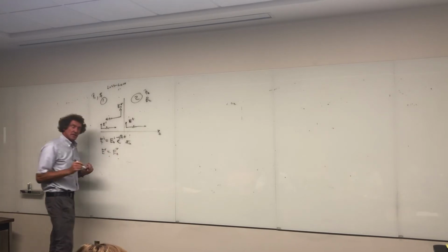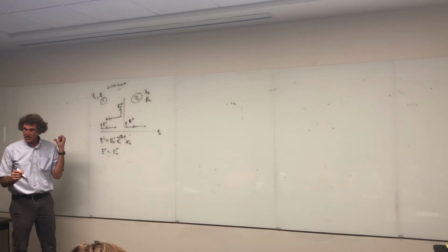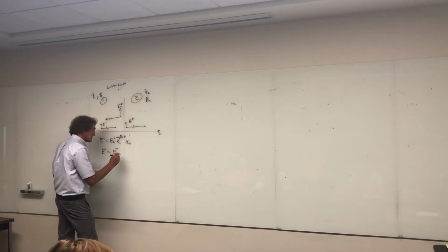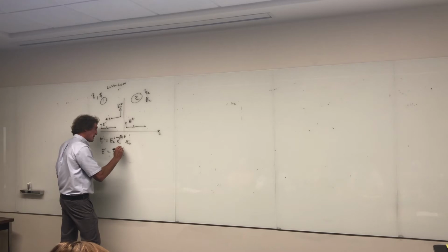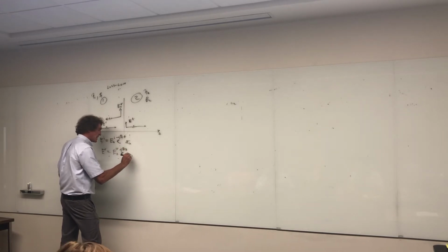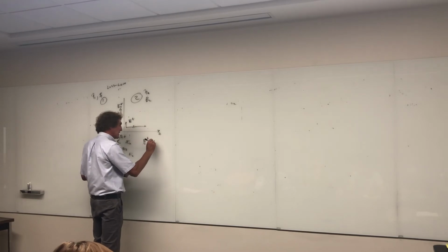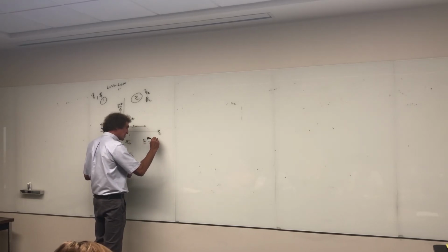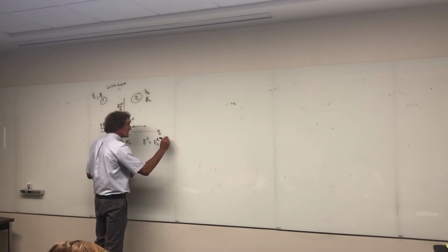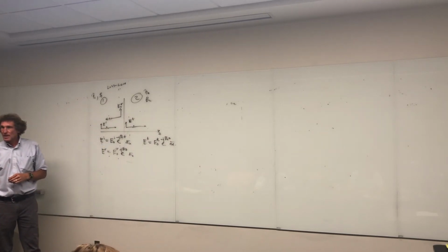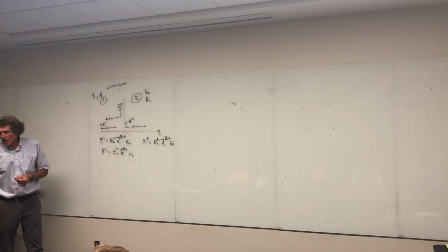Then what we're going to do is take E reflected, and it's going to have some E naught reflected, but it's moving in the opposite direction, right? The reflected wave is going away from that encounter right here. So it's e to the plus j beta 1 z a x. And we're also going to have a transmitted field. And that would be E naught transmitted times e to the minus j beta 2 times z a x. Are you all with me on that, class? This is our designations for that. Everybody got that?